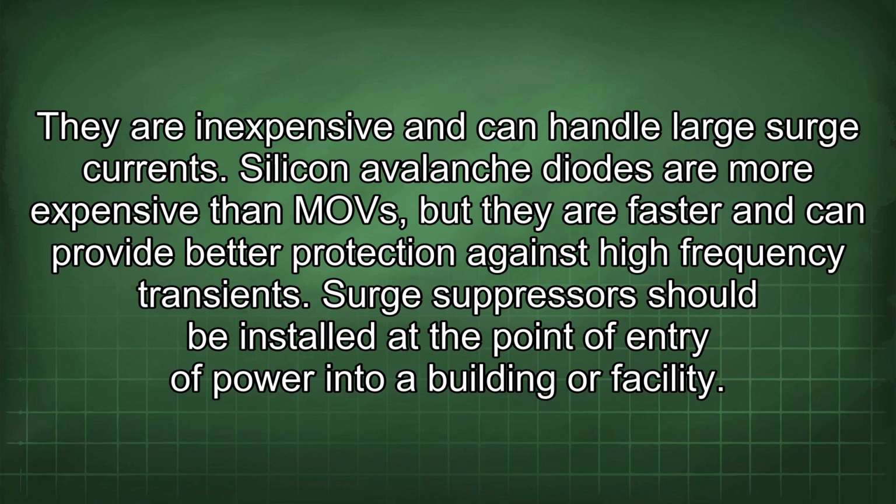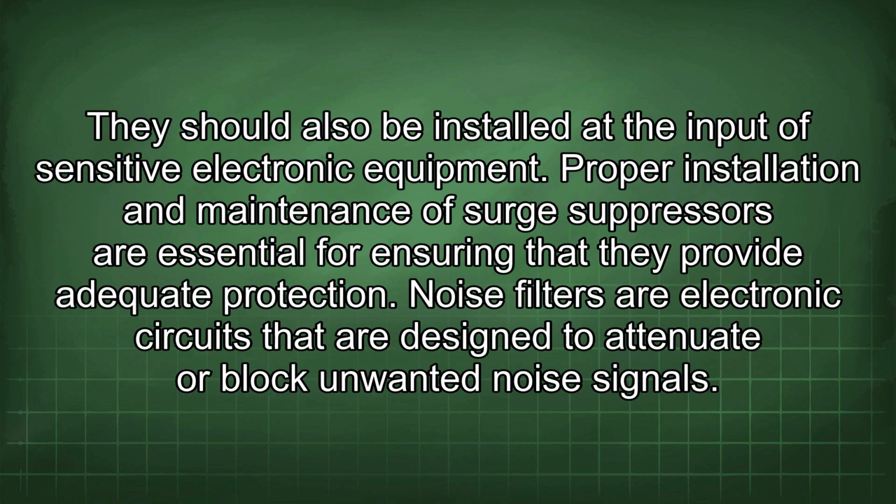Surge suppressors should be installed at the point of entry of power into a building or facility. They should also be installed at the input of sensitive electronic equipment. Proper installation and maintenance of surge suppressors are essential for ensuring that they provide adequate protection.